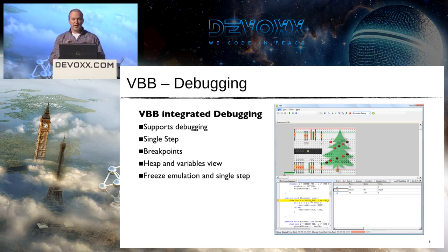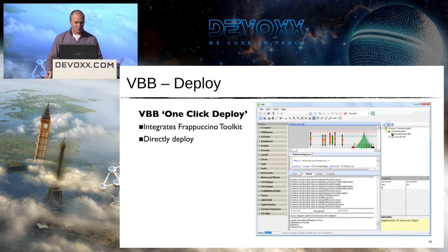It's the Java part of Arduino, but still extremely useful for developing Arduino applications, and a lot of people use that part. So it's become quite interesting to people because Arduino itself doesn't have some of these debug features that Virtual Breadboard does. So you can set breakpoints, you can single step, you can freeze your application as you're going along. It's quite a handy thing.